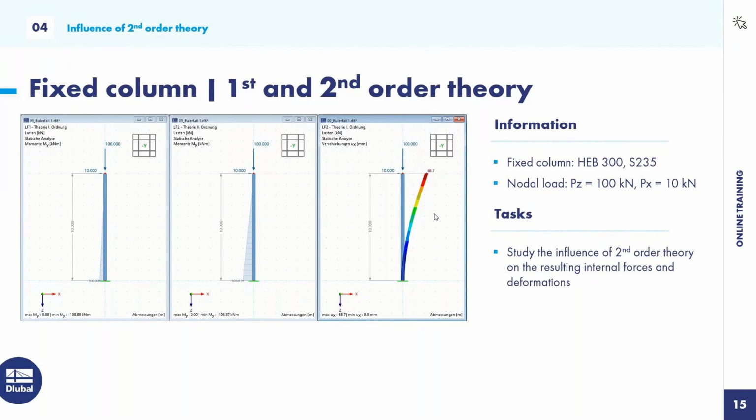So, to the background: so far everything we have modeled and calculated was calculated under the assumption of a linear deformation theory. So the equilibrium between internal and external forces was derived on the basis of the undeformed structure. Anyways, that's not always a valid assumption.